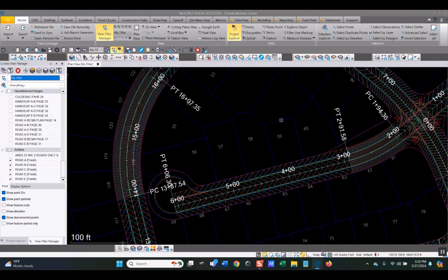Okay. Well, watch that line right there. Let's scrutinize this again. If I pick and hold this rectangle, but my rectangle touches or crosses the line, when you select with a solid rectangle, that's called select by window, and it only grabs the data that is fully enclosed inside the rectangle. It didn't grab that line because that line was not fully enclosed by the rectangle.